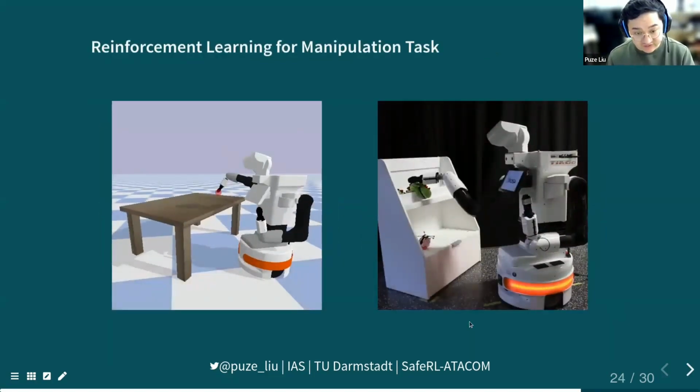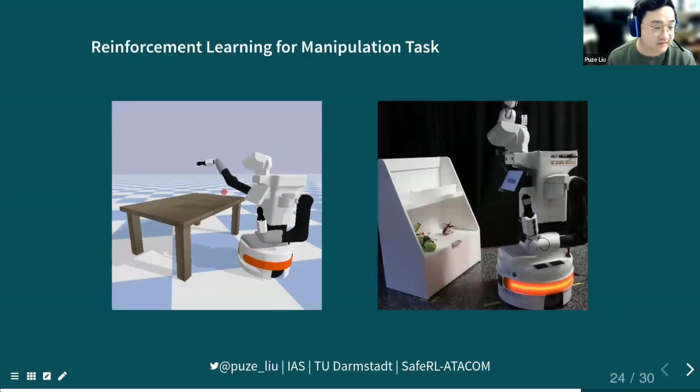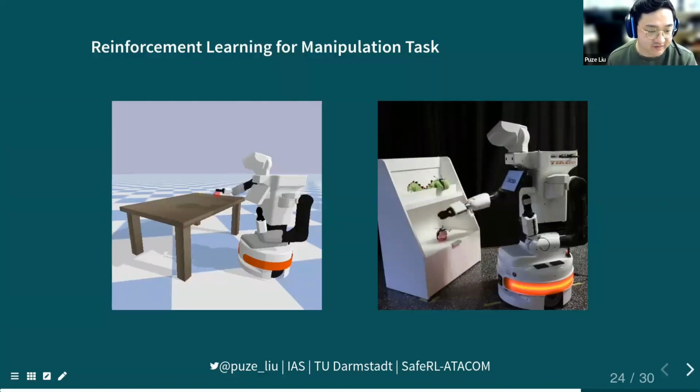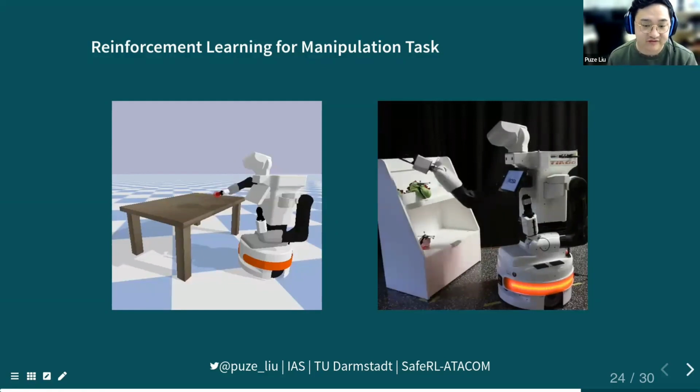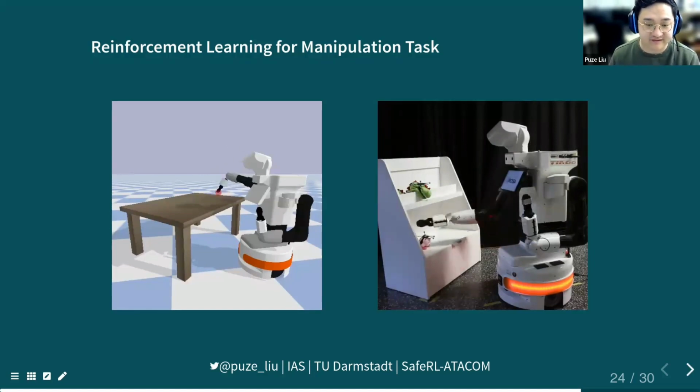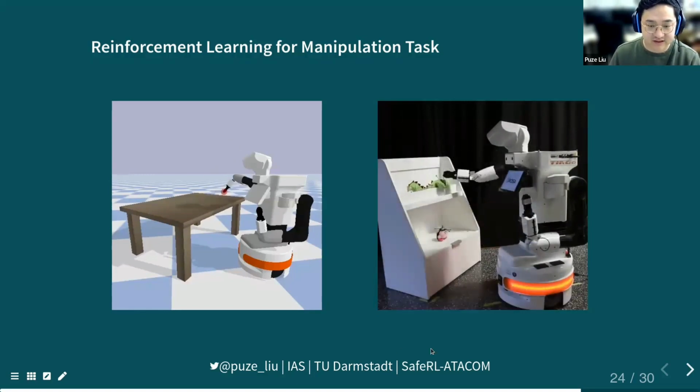We have also integrated this approach into safe reinforcement learning. For example, in this case, we integrated the trained distance fields of the table and the Tiago robot to achieve a goal-reaching task while avoiding collisions with the table and with the Tiago robot itself. Surprisingly, we train everything in simulation, but it transfers to the real robot without any problems. We train to reach a single goal, but if we put multiple goals on different points, it is also very easy to reach them.